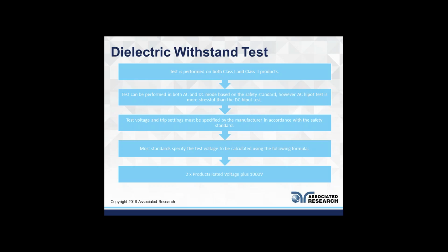Some of the trip points that you set on your hipot test could also let you know about the quality of your product. The standards care for breakdown, but if you really wanted to know the characteristics of your product, whether it was designed properly or not, you could look at the leakage reading. You might have a design change where the leakage reading went up. This could indicate that some components are not performing properly or not insulating as they should. So the leakage reading, even though it does not indicate a breakdown, could indicate something about the quality of the products you're using.